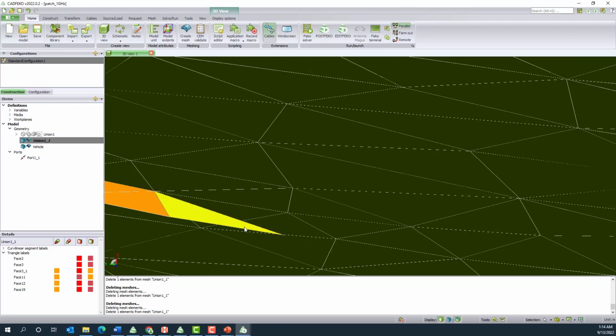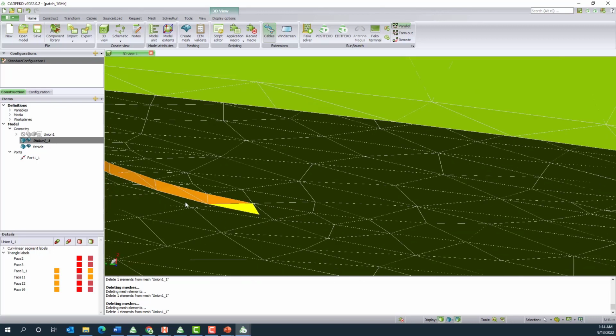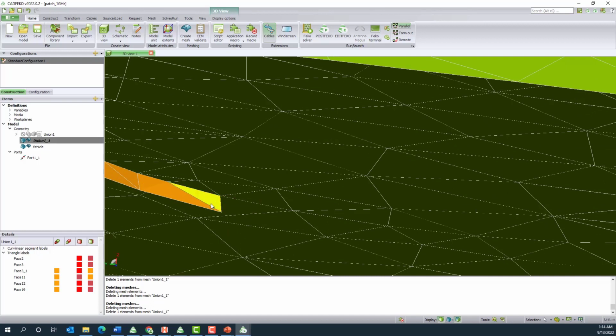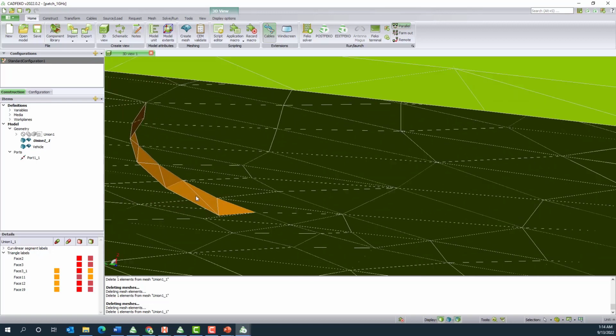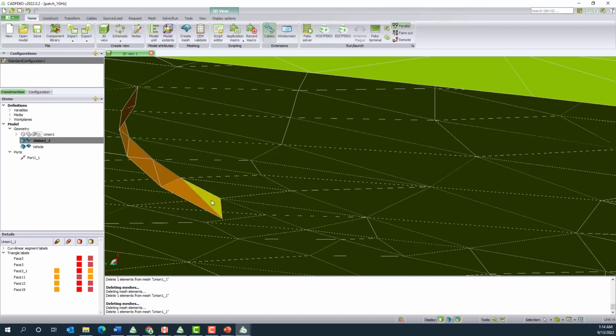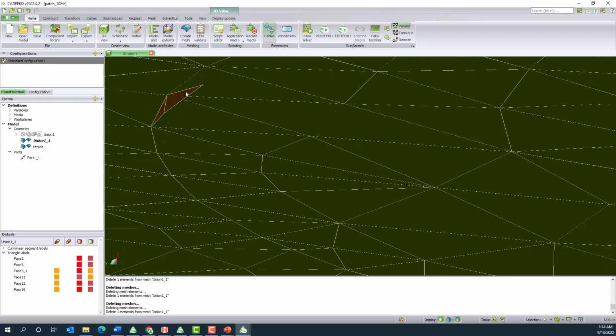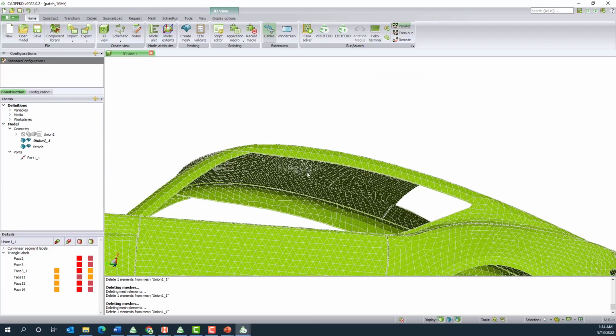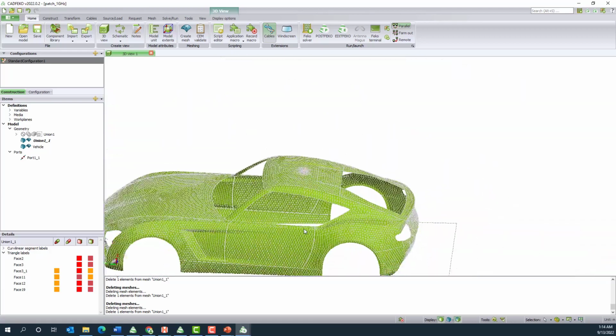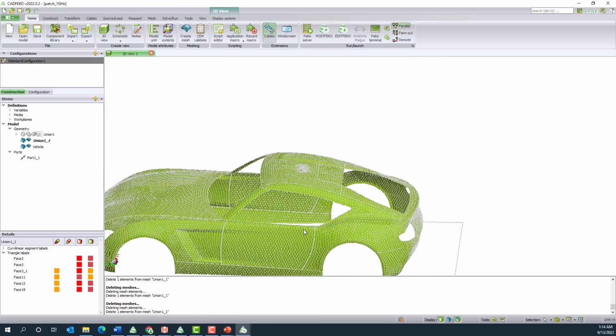Once we delete this particular thing, then we can run this geometry using the MLFMM solver, because it is an electrically large structure. That's why we are going to use the MLFMM solver. I am almost there. A couple more elements I'm going to delete. That's all. Last few more elements and last element. Okay, I got my clean geometry. Mesh boolean performed on geometry is available.